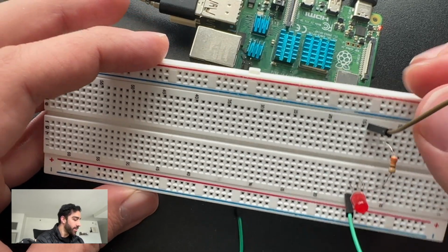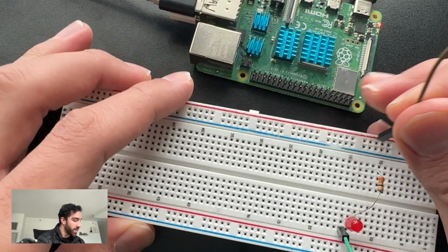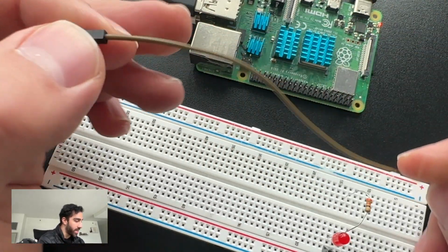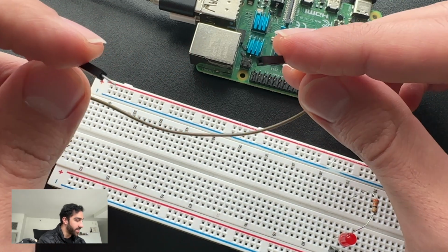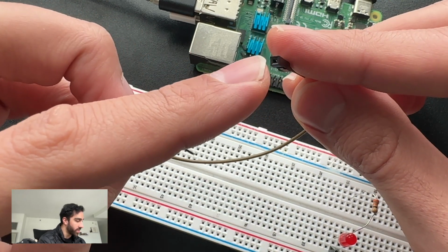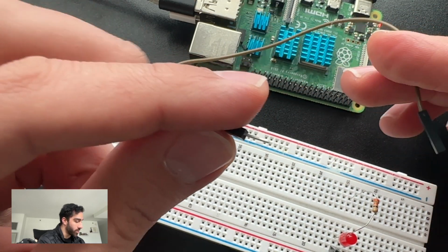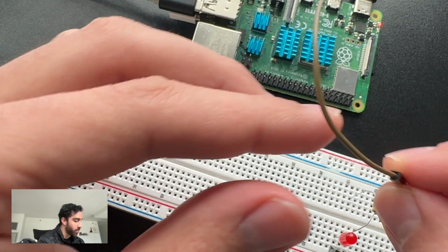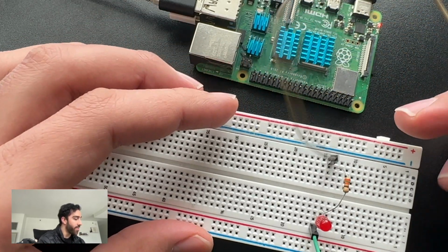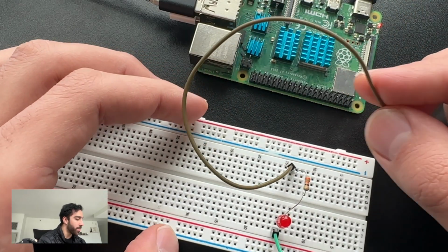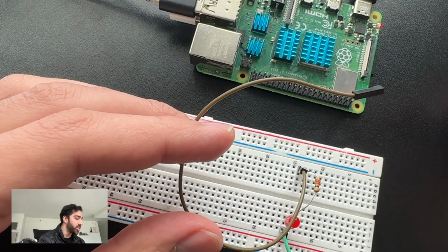On top of the LED, we have a jumper wire. This is called a male to female jumper wire. One end has a pin sticking out and the other end is insertable. This one we can insert into the Raspberry Pi, and this other end we can insert into the breadboard. So that's all we're doing. That's on the same row as one end of the resistor. So let's go ahead and do that. And this is what's going to be receiving power. This end is going to be receiving power from the Raspberry Pi on a GPIO pin.